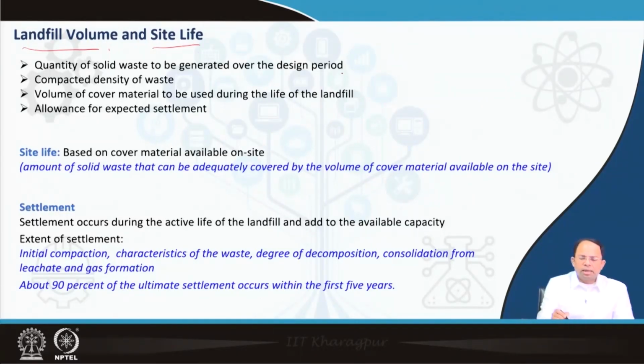So, this is determined based on the quantity of solid waste that is generated over the design period of the landfill. Sometimes we can decide the design period based on the land area available. Alternatively, if I know that I have to have a landfill which will work for so many years, then we have to determine a land area or proper site where we have adequate land area. So, in any case, we have to estimate the total landfill volume and the area required for it.